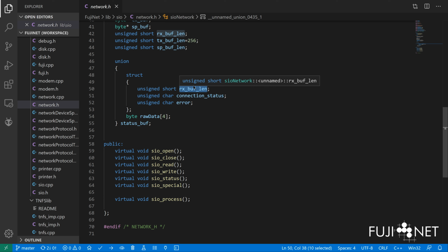And since SIO's checksum is essentially a simple 8-bit carryover checksum, you're going to get a lot of repeating values once you get above 128 or 256 or 512 bytes of a data payload, for that checksum to really be meaningful or any sort of a measure of integrity.